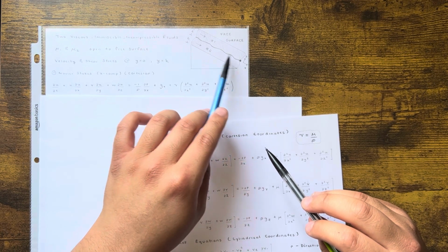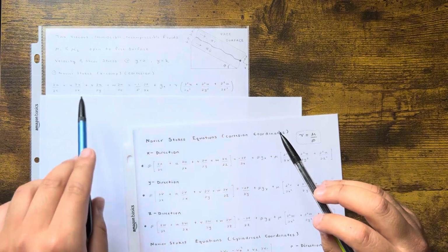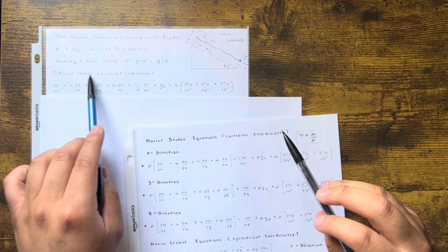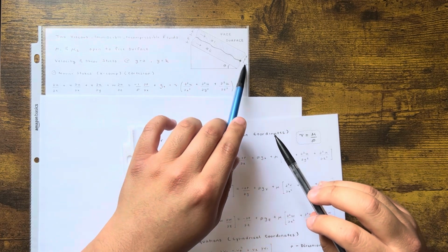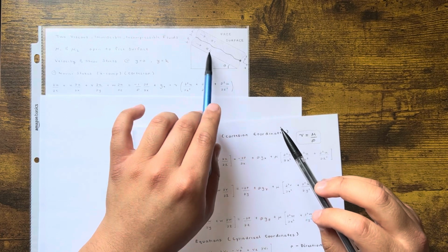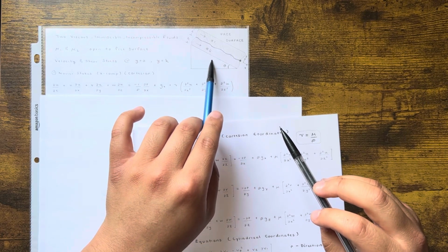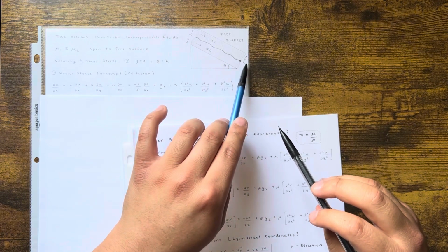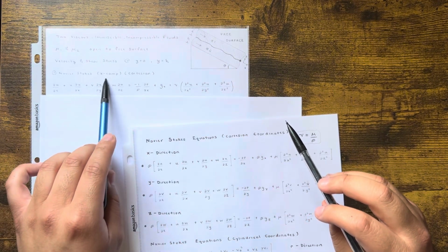If you do that, I'm sorry, my bad, you won't have two, you'll have one. But you'll have to modify both the x component and the y component of the Navier-Stokes equations. It's better to just tilt it and get that g sine theta, and you'll see how we get it. It's better to just tilt your axis. That way we only deal with the x component.